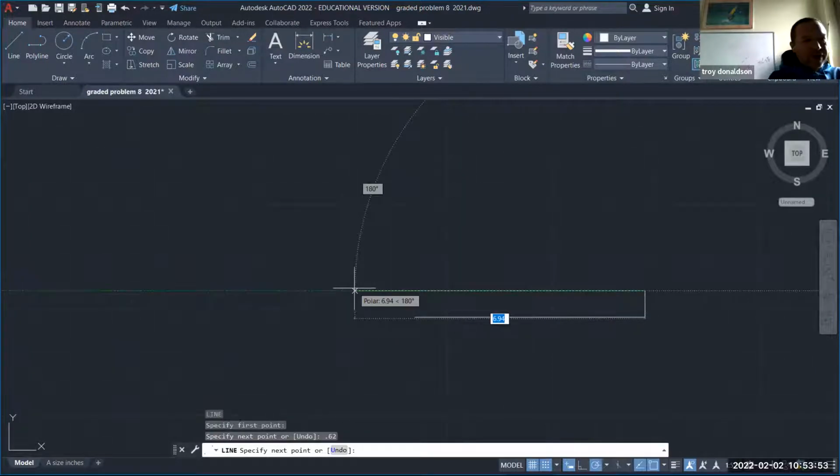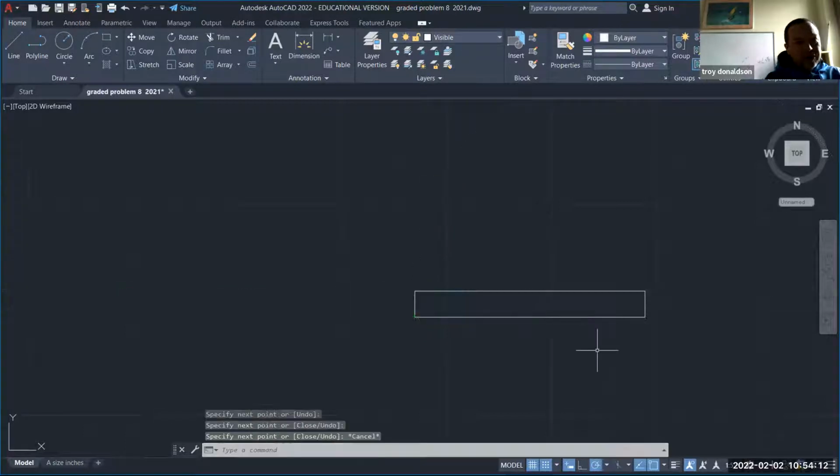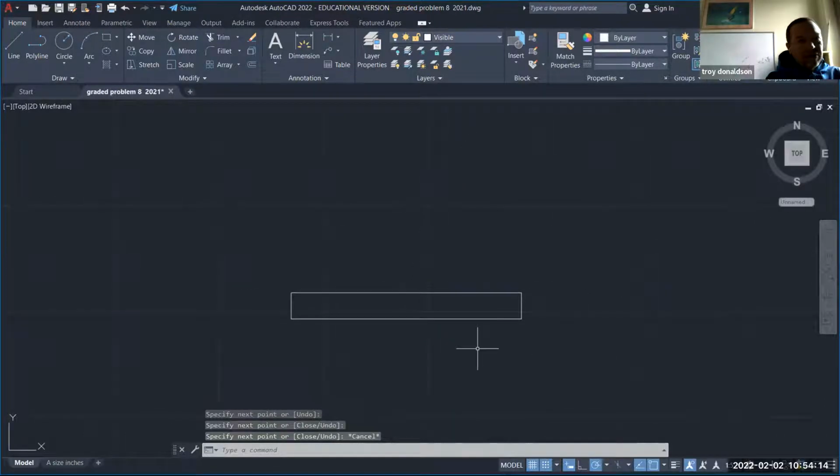You can also mouse over this and pull it up, right? And I'll have a vertical. So if I settle the mouse in the right spot, it'll connect the two. And that's perfect. As long as those green extension horizontal and vertical lines are showing, when I click, it does it automatically. So the more you get used to that, the easier drawing will be using those ortho controls.